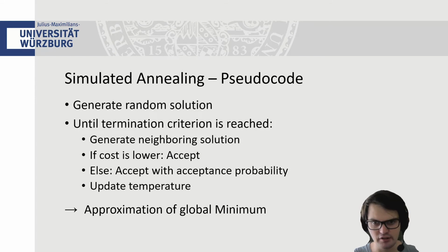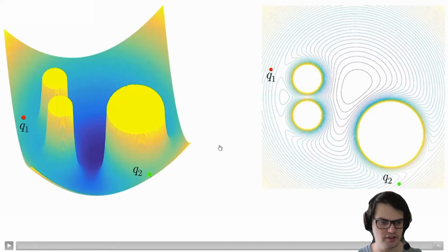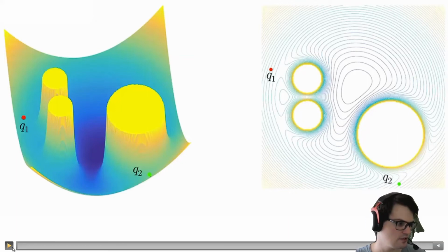Applying simulated annealing for path planning can be done in several ways. You could either design your own algorithm, which is completely based on simulated annealing, but you could also use it as an auxiliary algorithm, which is also commonly done. For example, here with potential fields. In this example, you can see a potential field, and in the middle is a goal, and there are some obstacles with repulsive forces, so these ones.